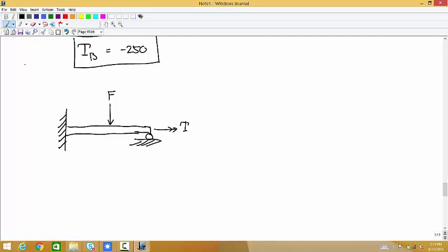Sometimes with that kind of stuff, you pretend that the joints are something else. Like, when we talk about trusses, everything's connected by pin joints. If you look at a real truss, you see something like this at the joints. That's not a pin joint. This doesn't allow free rotation of those members.